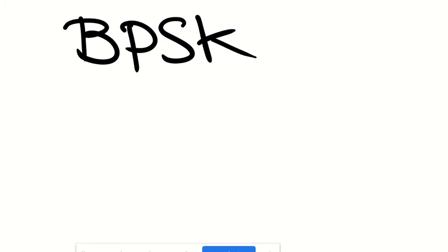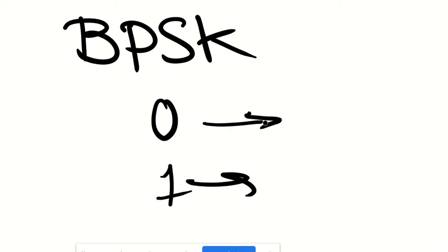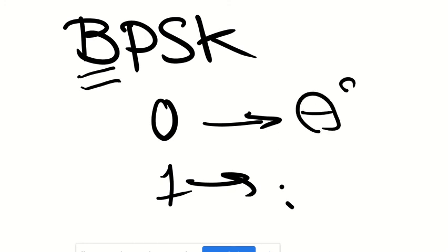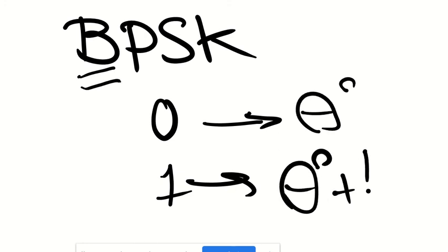During the time that the binary is 0, the carrier signal is, as I said, transmitted with one phase. When it's 1, the carrier is transmitted with another phase. For binary, if there is a phase here for 0, then for 1 that would be that phase plus 180 degrees phase shift.